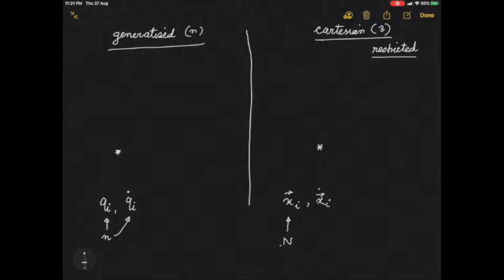So this is configuration space and the Cartesian space velocities. And why do I need to choose the velocity? Because I know qi at t. So qi at t plus dt is nothing but qi at t plus qi dot dt. As I said, this is my choice. So I choose any velocity, and once I choose a velocity, I go to another point.